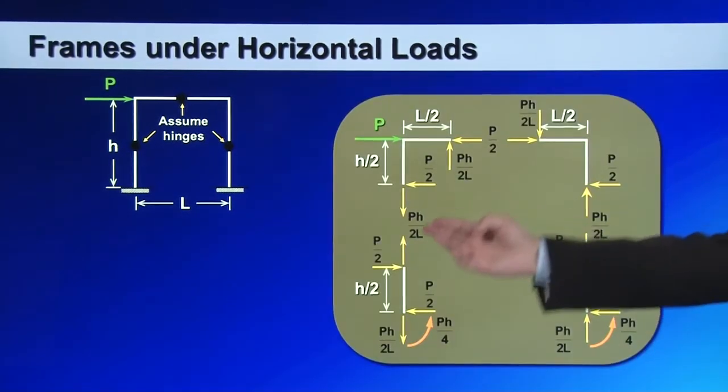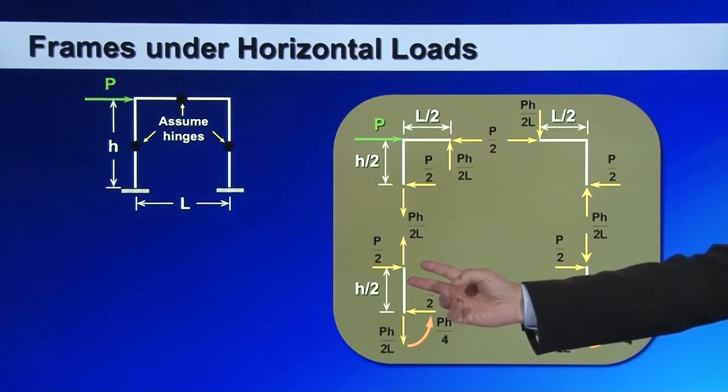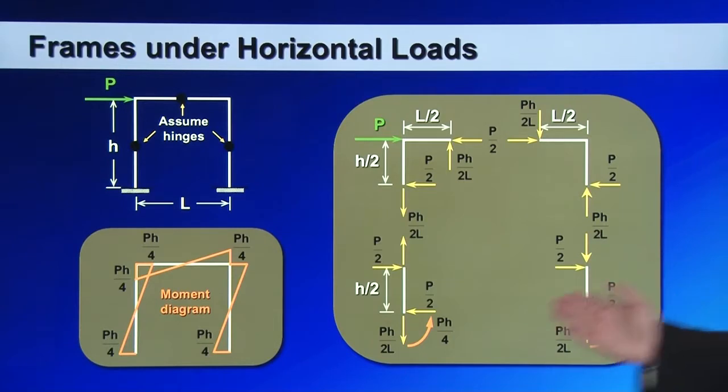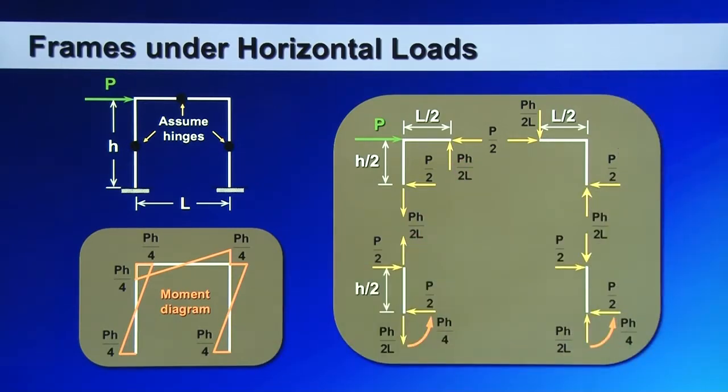Then you do action and reaction. You carry these two forces to the lower part of the structure, and then carry on with your equilibrium analysis. Then you will be able, after that, to plot the bending moment diagrams.